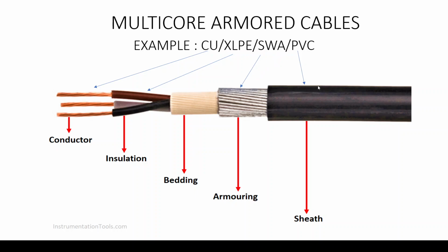Then you move to the final component, the final cable sheath, the enclosing part of the cable, which is the outer, visible part of the cable. So in this case it's PVC. This one can either be PVC, or it can be LSF, which is a low smoke and fumes emitting material, but again the most commonly used type is PVC. So let's summarize it here. Cu is the conductive part. This can be aluminum or copper, so it can be Al, for example, or Cu.